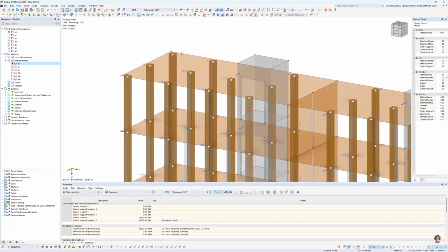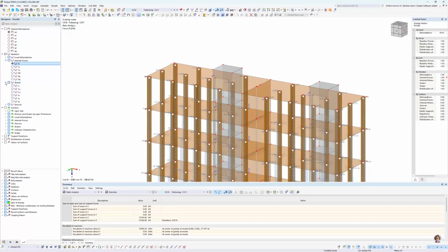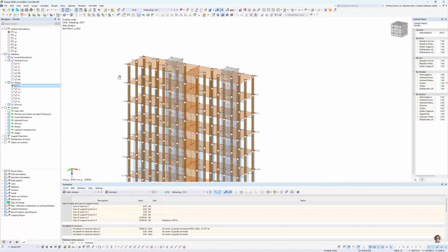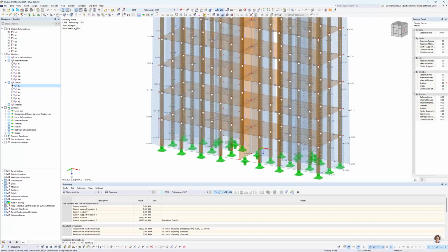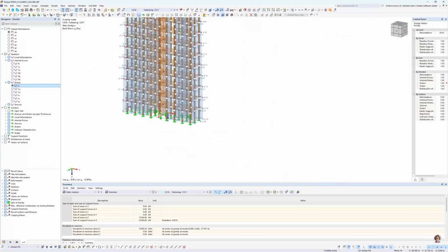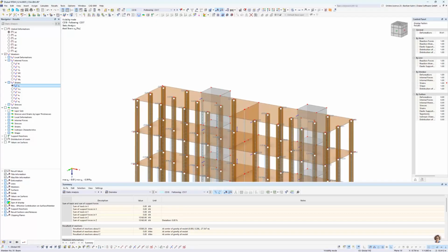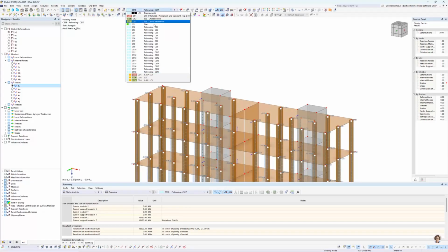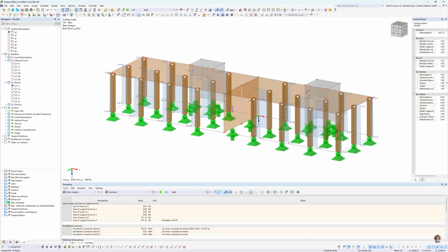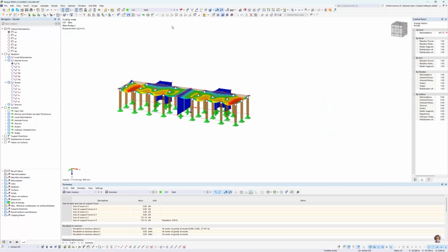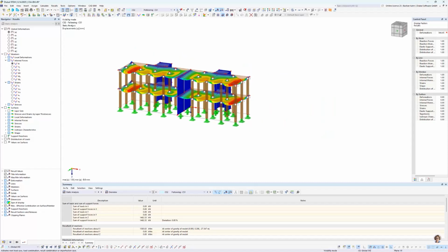Okay, so and now let's take a look at the normal force again, because that's probably the point where we are hanging on, and you see, so that's quite similar to what we had before. Take a look at the strain in this. So you see on the top story 0.03 and on the bottom 0.18. And maybe that's probably very interesting. If we go now, remember this strain, and go for the first story. No surprise, but the strain here is similar to what we have in the top story in the 18th building, and it actually will be the same with all the others.